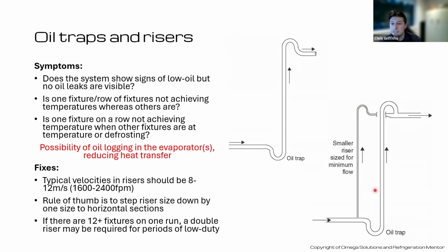So why don't we do this on every system? It's a lot more pipework. It's very difficult to make look tidy as well, which I know a lot of end users, particularly their merchandising teams, care about. Unless you have large boxing in, you're going to have what most people would see as a mess of pipes. I think they look pretty good, to be fair. We don't see them very often in the UK, and particularly not on CO2 systems. So when you do come across one, possibly left over from HFC, it's quite a special thing to see. But I just think it's a great engineering solution.